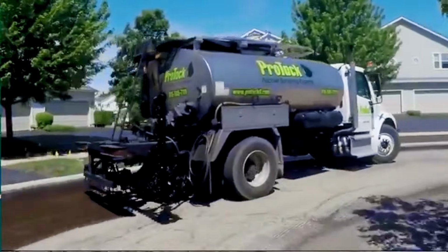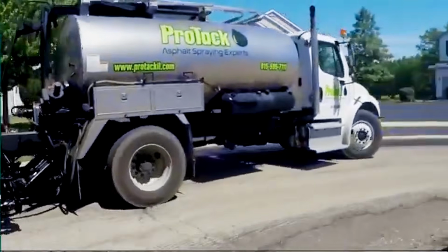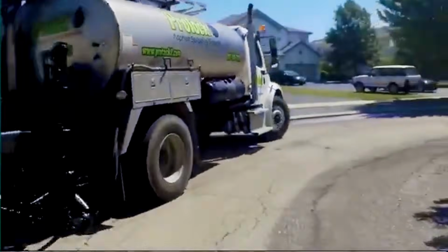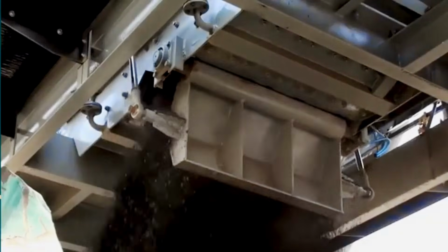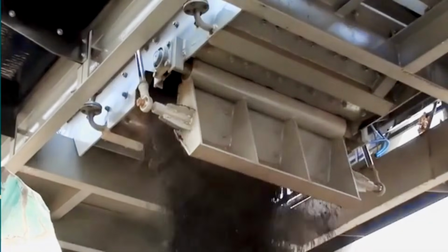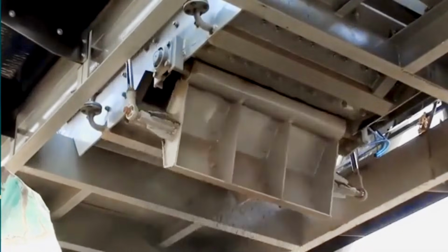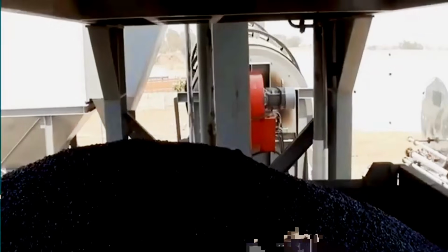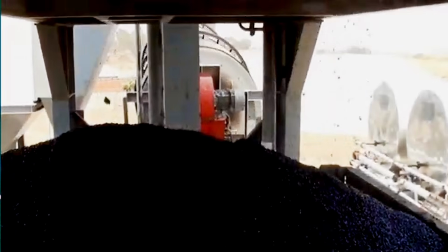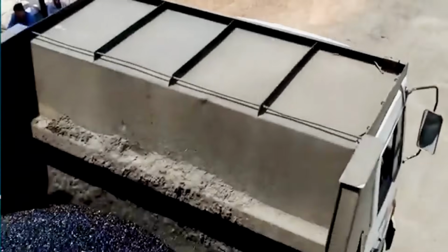Prime coat or tack coat shall be applied as per specifications. The DBM mix shall be produced in a hot mix plant on a batch basis by weight. Mixing shall be carried out in a twin-shaft pug mill to produce a homogeneous mix. The mixture shall be transported from the batching plant by tippers, and if required, shall be covered with tarpaulin to maintain temperature and prevent dust spread during transport and laying.